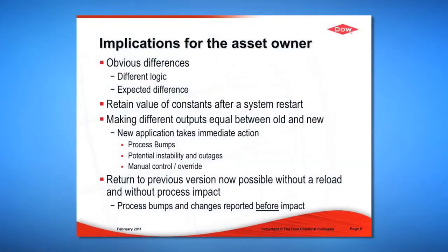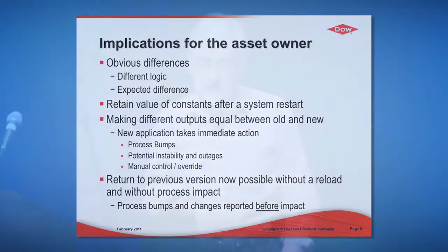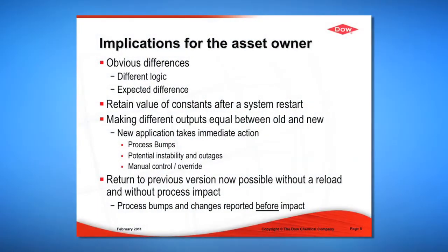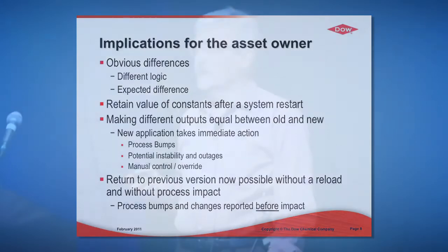Some of the other implications for the asset owner, obviously, are being able to evaluate those differences, looking at obvious differences in logic and expected versus unexpected implications. Look also at what happens after a restart of the system. You would need to be able to preserve state, start it up, look at it and say, is it where I want it to be? Looking at the outputs, making sure that they're equal, old and new.